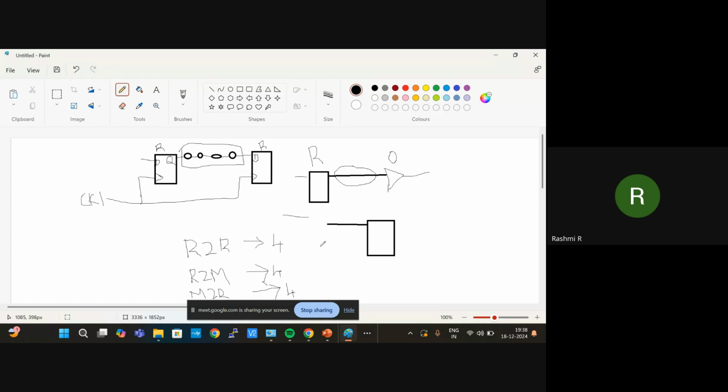Before optimization, we will do group path. Group path will give some commands to the tool. Group path hyphen from all registers to all registers, then it will pick reg to reg paths. Or else group path hyphen name reg to reg. Next, for reg to mem, we will filter memories from all the cells, and there we will give the weightage.